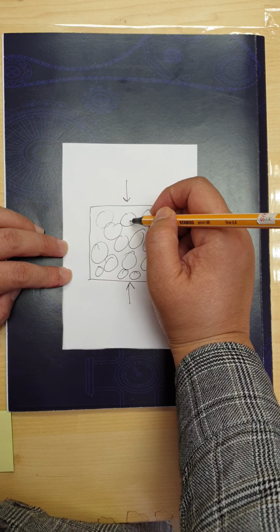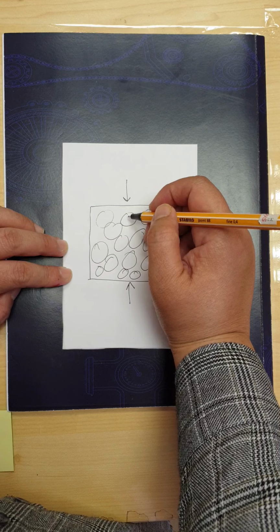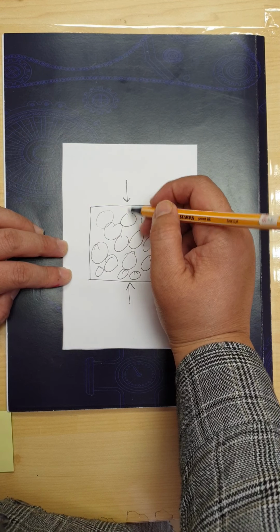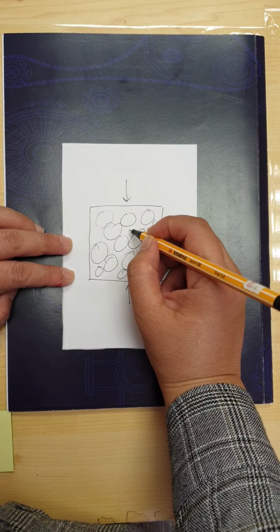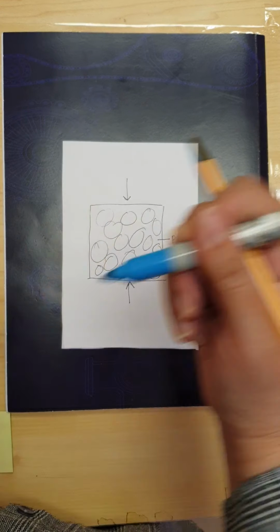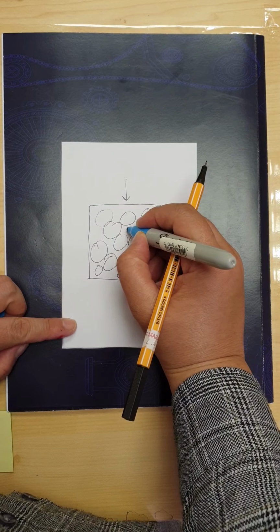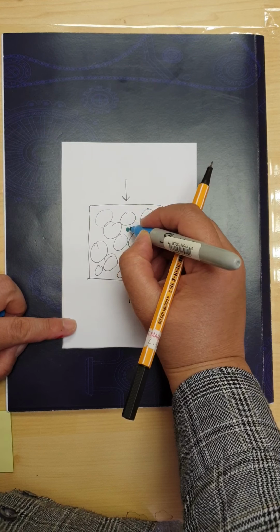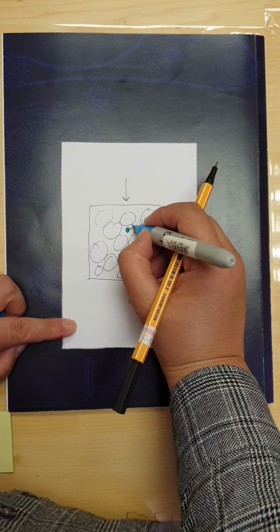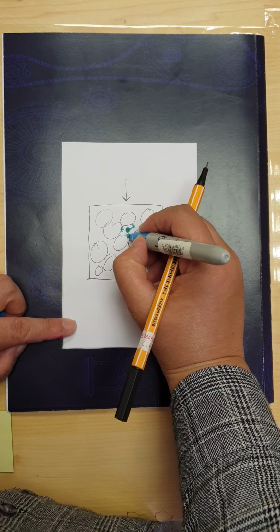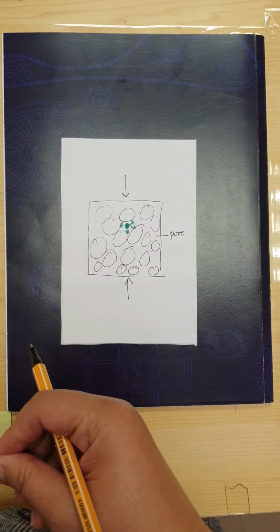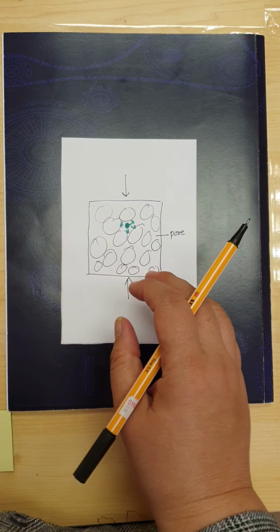This soil will act back to push against the load, to counter the load, and at the same time, this void is occupied by pore water pressure, which will also act to counter whatever stress acts on your soil.